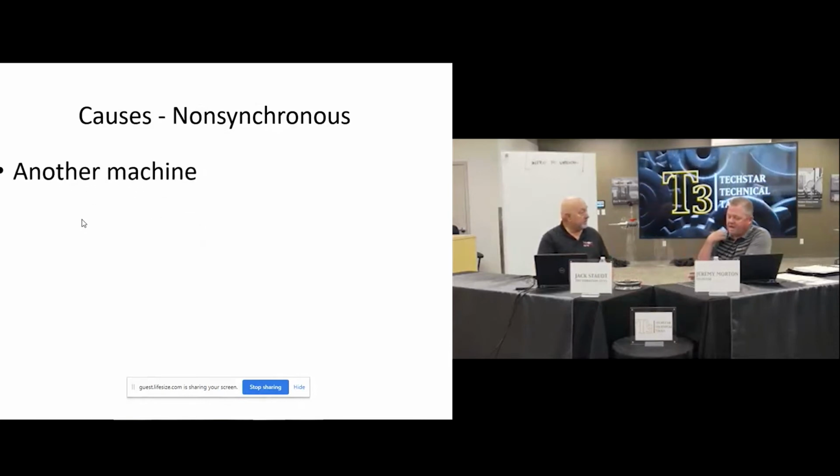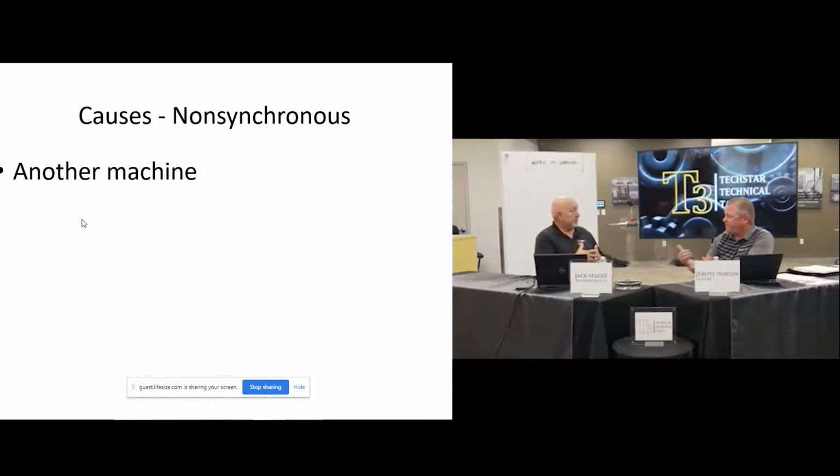So if a machine doesn't have, I know you mentioned earlier being able to look at a synchronous spike on some of the analyzers you use and be able to calculate a running speed. Do you typically go and install some sort of a temporary phase reference on that machine to capture that synchronous data? Yeah, if you're going to get more into the analysis, that's what you'd want to do. You want to do some type of maybe order tracking. Would it be like a magnetic pickup, or an optical sensor looking at a piece of tape?